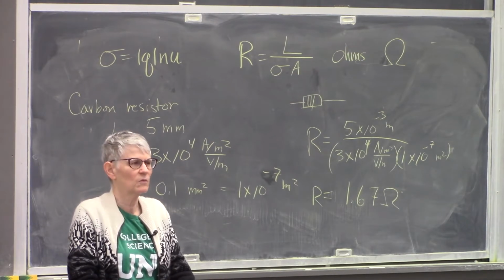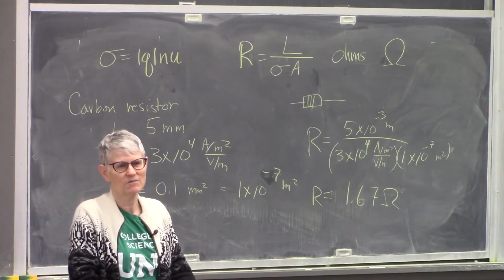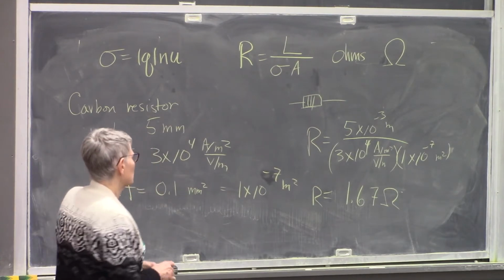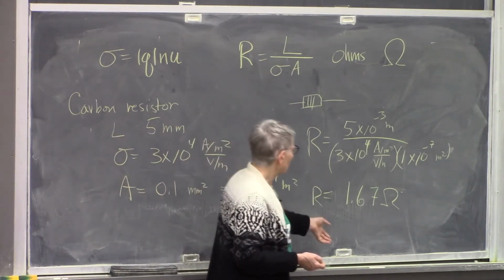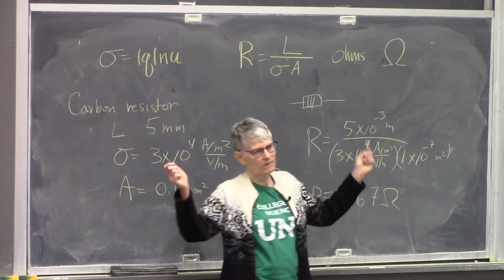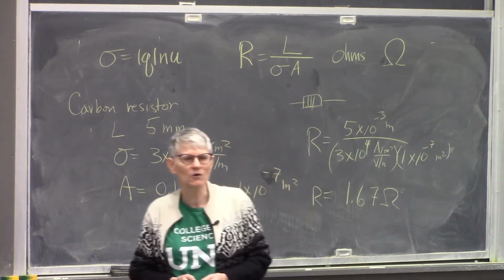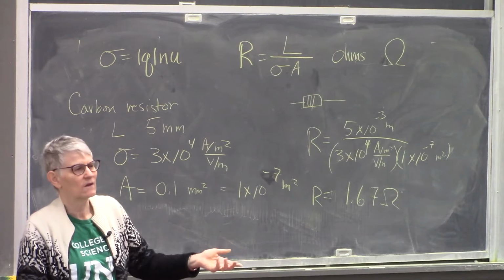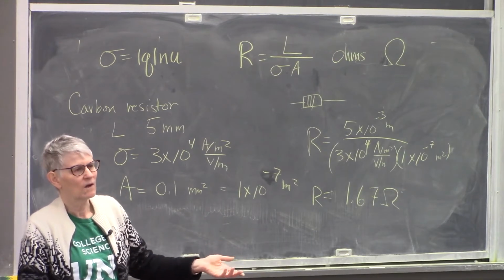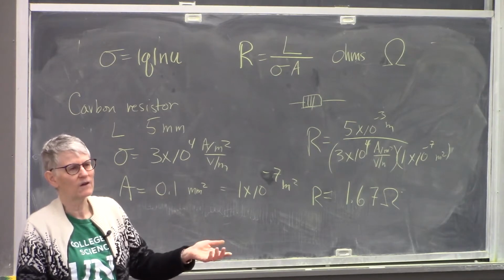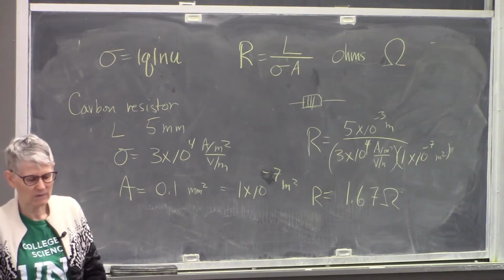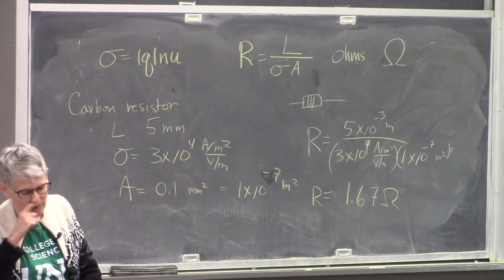And you'll find another nice thing about using these sort of conventional units in circuit analysis is that we're working with numbers that are a lot smaller than 10 to the 18th electrons per second, and cross-sectional areas and whatnot. Resistors are typically, you know, an ohm to a few hundred ohms that we might be working with. Currents are in the range of a hundredth of an ampere to a few amperes. You know, so the units just are kind of nice.